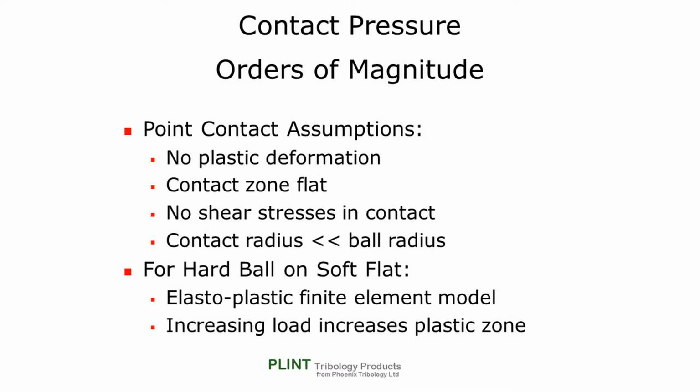Of course, we should remind ourselves that in the case of the point contact, we may not be justified in using the Hertzian contact equations. For these to be true, it is assumed that the contact is elastic, that the contact zone is flat, that there are no shear stresses in the contact zone, and that the contact radius is much smaller than the radius of the ball.